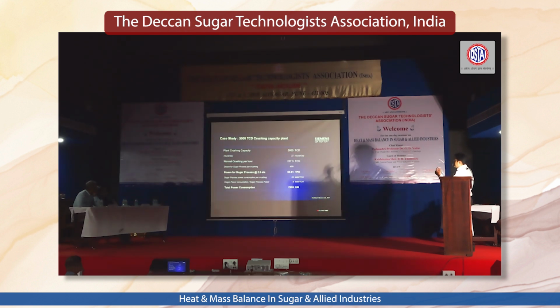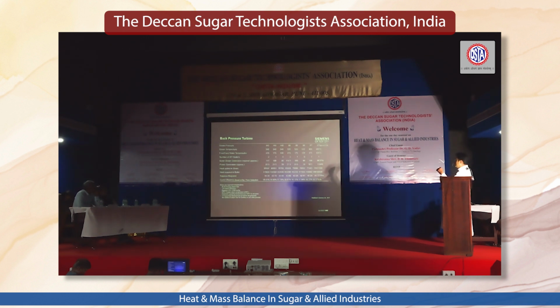So this is one case study for a 5000 TCD plant where we have made some assumption that the steam required is 40%, so with that 90 TPH process steam is required. As we understand, we now also have plants with 30% sugar process steam, so it will reduce to 70 TPH. It will only change our figures, but the trend will remain the same. So here are some trends.